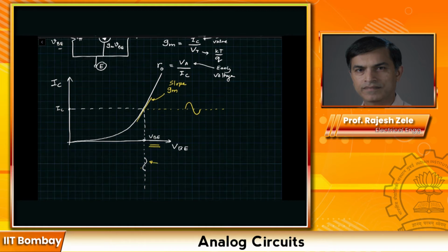This is an important point because we are used to thinking there is an inversion going from base to collector. However, the specific question I'm asking is: if VBE increases, then the collector current should also increase.